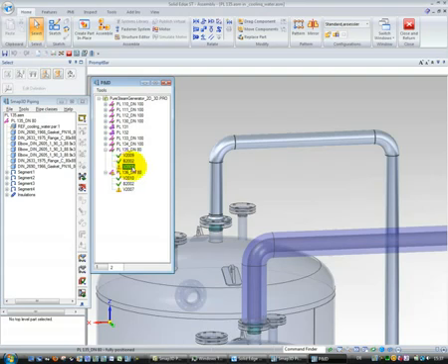If this is not the case, that in your company or in your department valves do not belong to the pipe spec, then you have to place these valves manually and interactively, like I showed you with the vessel. But in our case it depends on a pipe spec, and because it does, we can say place this fitting to the CAD environment.